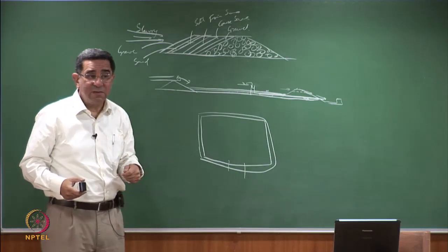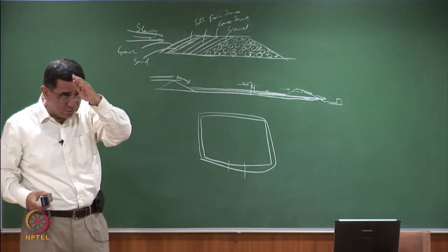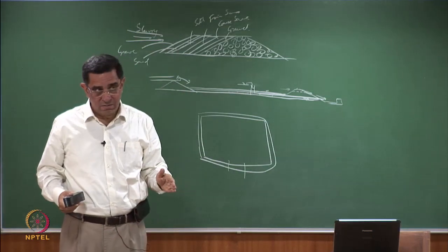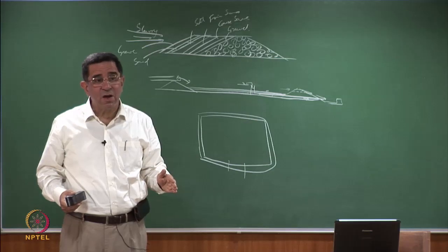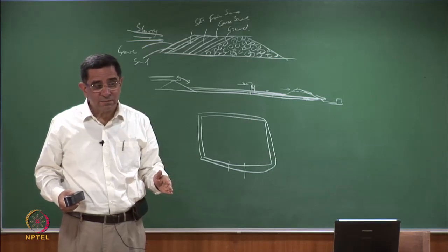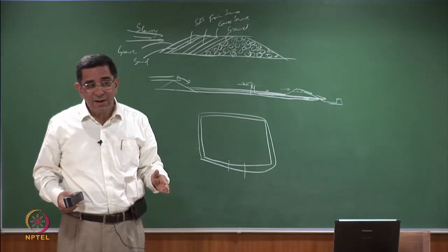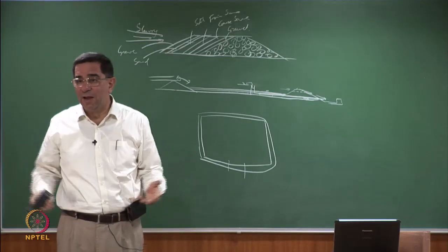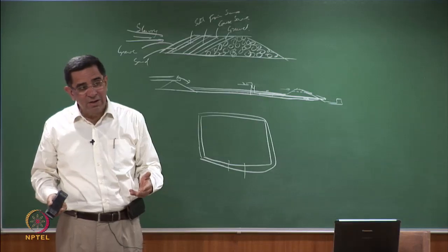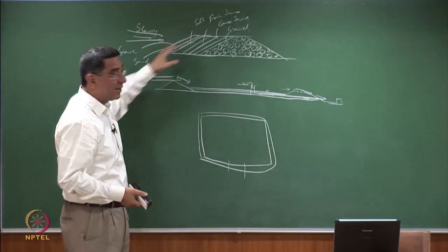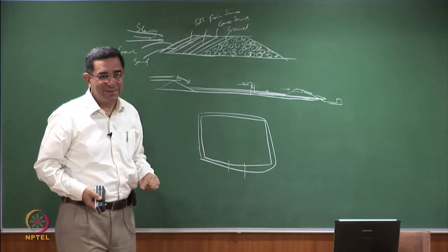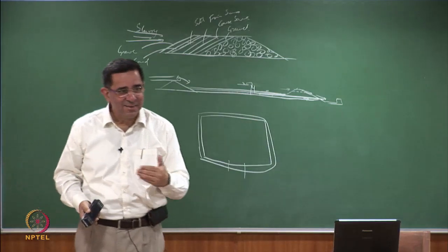However, if instead of all this I was to make this whole arrangement but have a geotextile filter, then I could replace the geotextile filter. That's what we are doing in a bag filter. The only thing is that the geotextile filter is progressively getting buried in the slurry which is deposited. Can you see the engineering here?